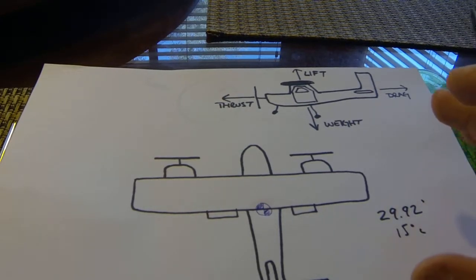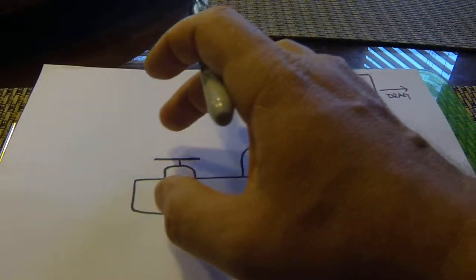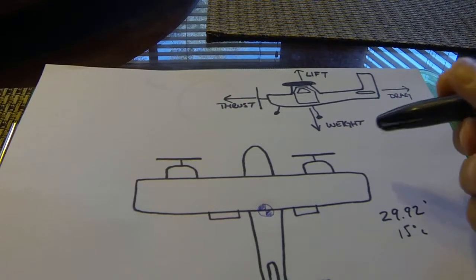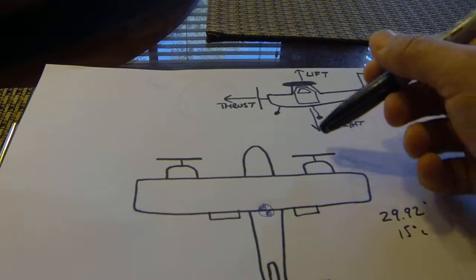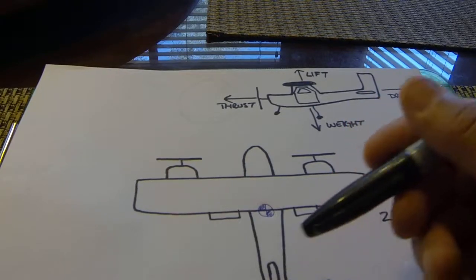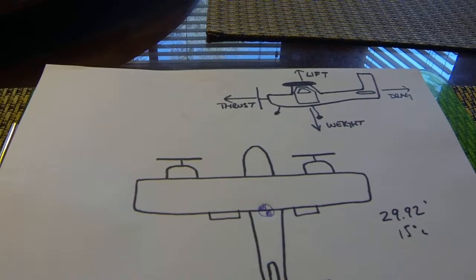That's going to be the best conditions to provide maximum power by our operating engine. The higher we go in altitude and in temperature, the worse our engines are going to perform. The higher the density altitude, the less thrust vector we're going to have, the less turning moment we're going to have, and the better our rudder will be at directional control.